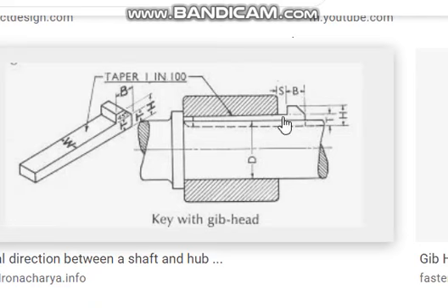Here you see, this is a jib-headed key. This is a shaft which has an inbuilt collar, an integral part of the shaft. When it is integral like this, say you inserted the key. For inserting the key you had access, but for removing from this side, you cannot remove it. Why? Because there is a collar.